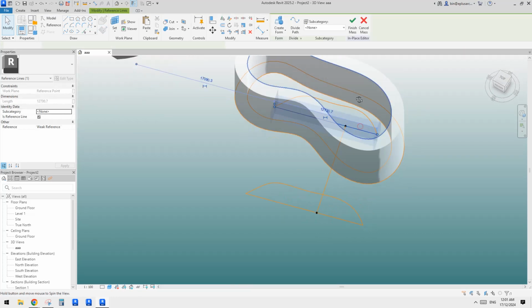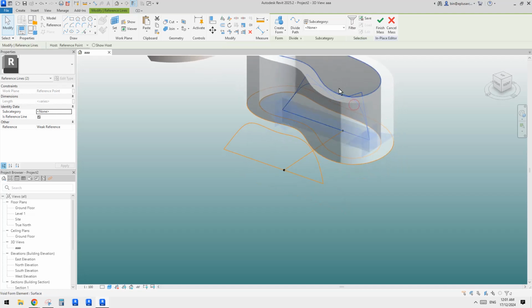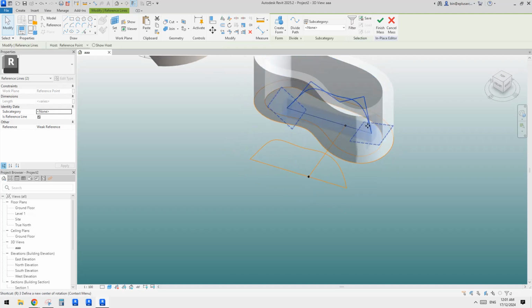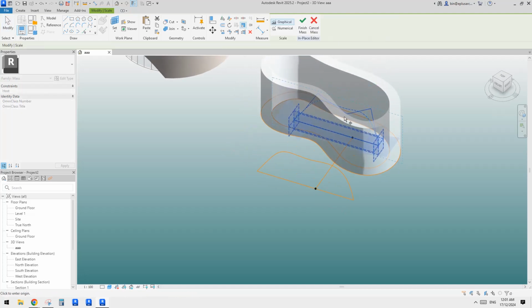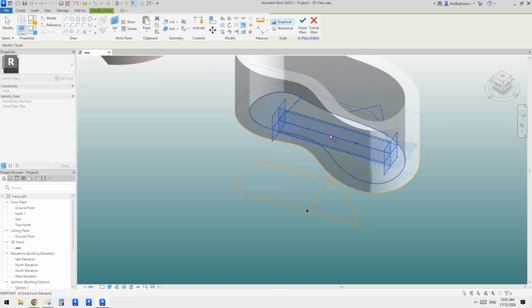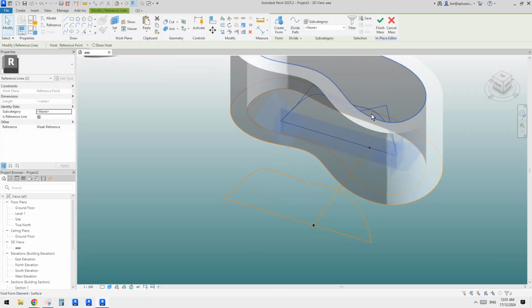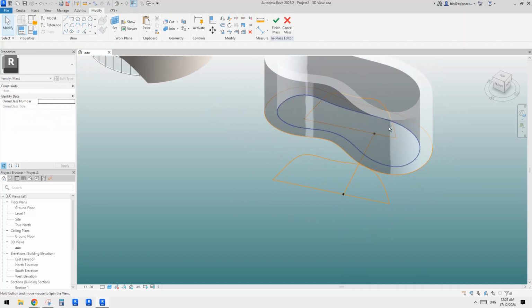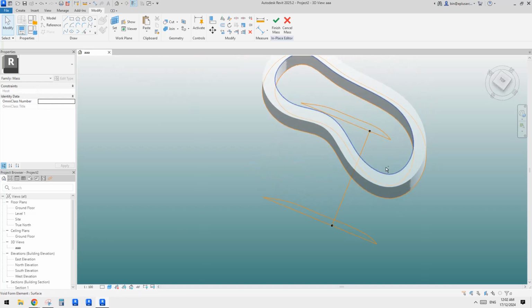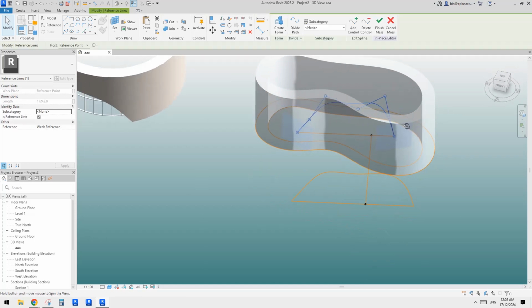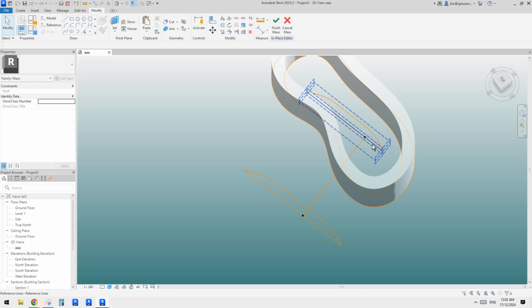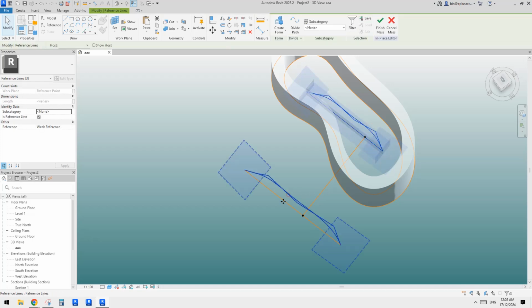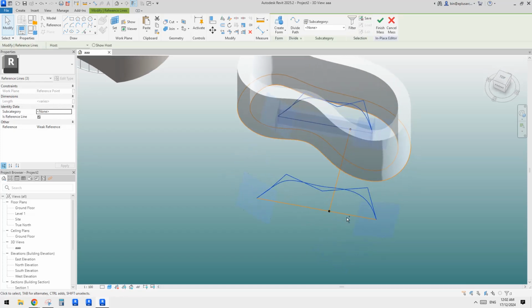So you can also, if you don't mind the height of this profile, use scale, like you can type RE, and then you can just scale it down a little bit. And after that, if you want to change your mind, you can still change the profile again. So now we have these two profiles, right, different sizes, and then we can just create something from them.